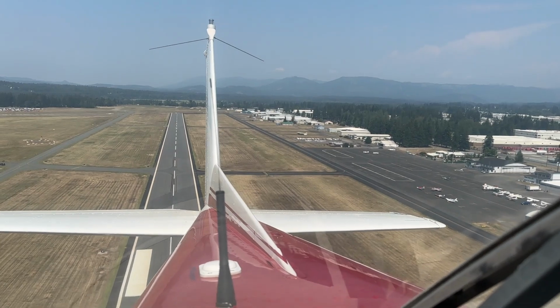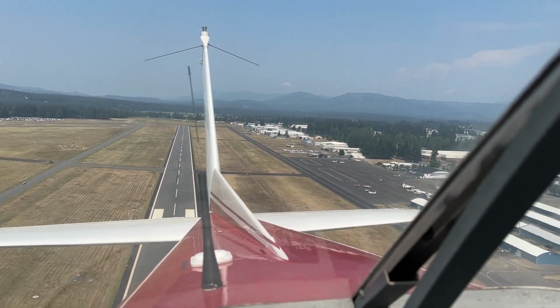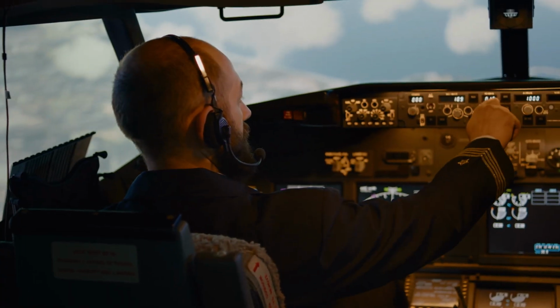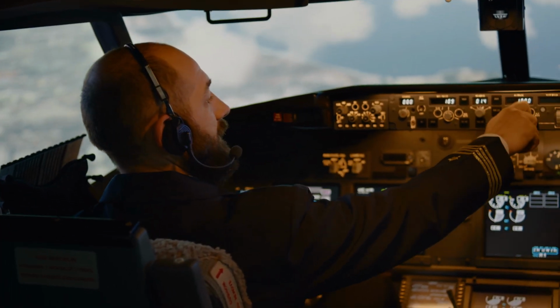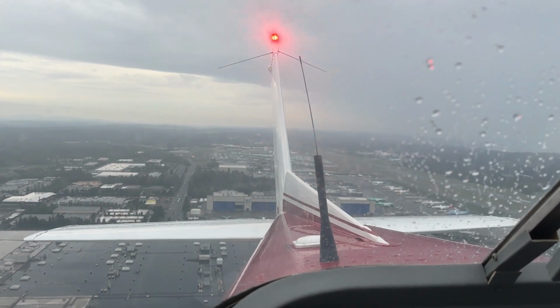Maintain positive control of the aircraft as you climb out, and once you've cleared your obstacles, you can raise your flaps all the way. The absolute last step is to make a radio call to the tower or surrounding traffic that you're going around. Remember, cram: climb, course, clean, and call. As always, we aviate, navigate, and then communicate. Fly the plane, know where you're going, and then make your radio calls in that order.